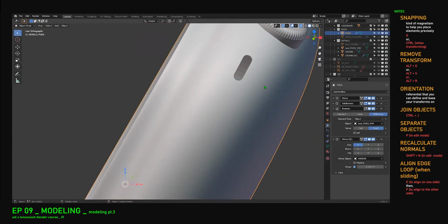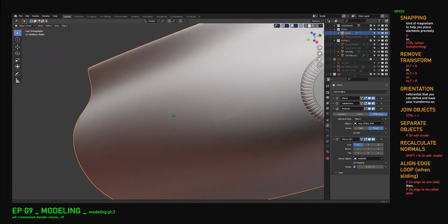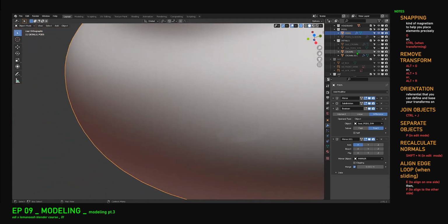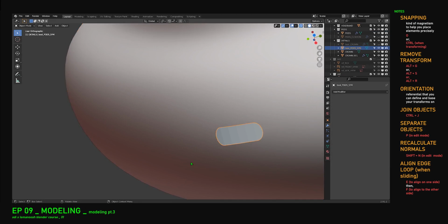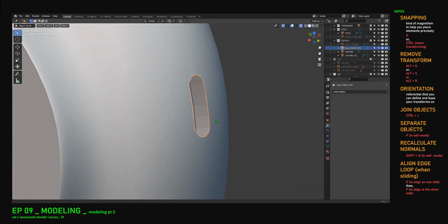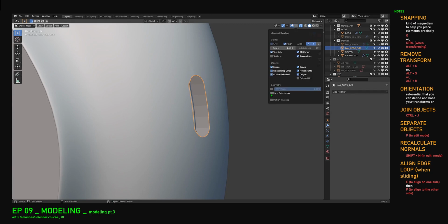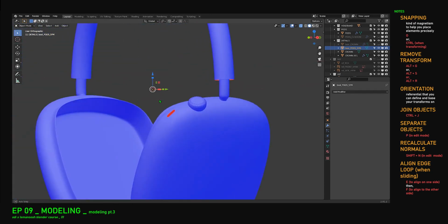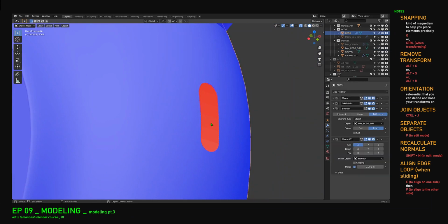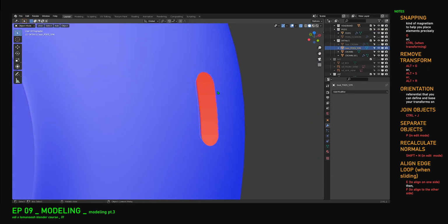So it doesn't want to do the boolean, and this is probably because you can see that there is some weird thing happening, but if you see the boolean, the shader looks like it's a bit different. And if you go here, in the overlays, you have face orientation, and you can see that everything is blue but this button. So it means that basically the surfaces are pointing inward and we just see the back face of the surfaces.